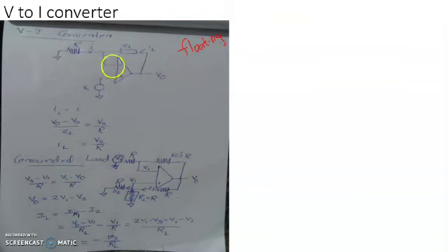Now practical current to the op-amp is 0. So all of this current flowing through the load will be taking this path, and since the voltage at this point is Vs, this voltage will be appearing here since there is no current to the interior of the op-amp. Then IL equal to I, that is current through this path.